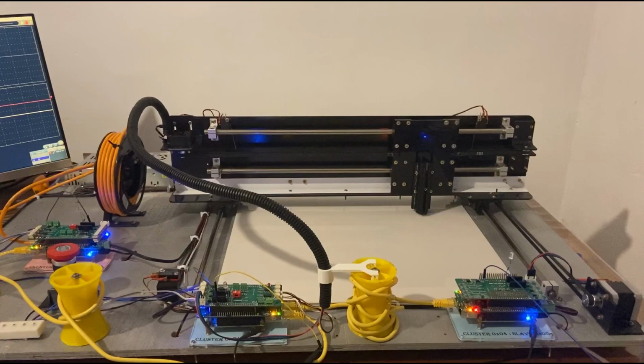In the third scenario, we are demonstrating how the system handles a broken link situation. Here the emergency is handled in 2 ways. Once a link gets disconnected, the slaves in the link from there onwards will call emergency locally, as they have no connection with the master anymore. Slaves in between the master and the disconnected link will get an emergency from the master.